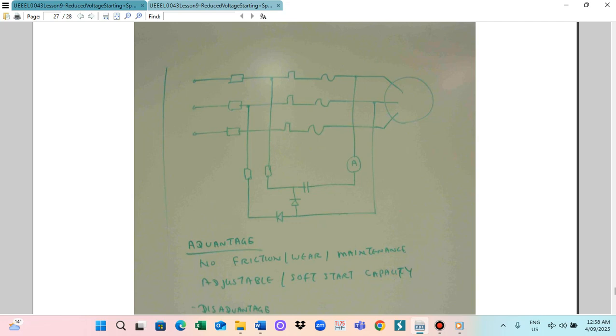When the motor runs, the brake is holding the motor shaft, yet the shaft also rotates. Rotating means that the brake is catching the liner, so this is why the motor is hot. This brake is the problem. The brake didn't release when you ran the motor, so the motor got hot, which is like a high load on the motor. When you stop the motor, the brake is applied, so the motor will cool down.